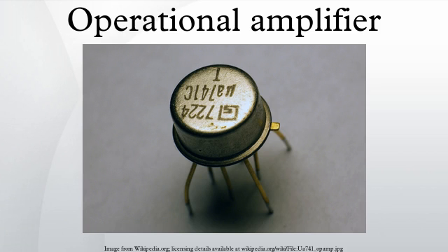Operational amplifiers had their origins in analog computers, where they were used to do mathematical operations in many linear, nonlinear and frequency-dependent circuits. Characteristics of a circuit using an op-amp are set by external components with little dependence on temperature changes or manufacturing variations in the op-amp itself, which makes op-amps popular building blocks for circuit design.